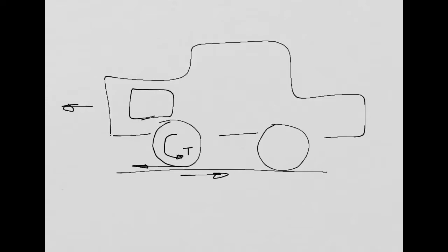So how do we calculate this torque? This torque, T, basically is going to be what? Imagine the wheel has this radius R, the radius of the wheel. This torque is going to be equal to the radius times the force, this force F. Right? This is the definition of a moment. It is a force times a length, in this case the radius of the wheel. And that will give you the torque that you need.